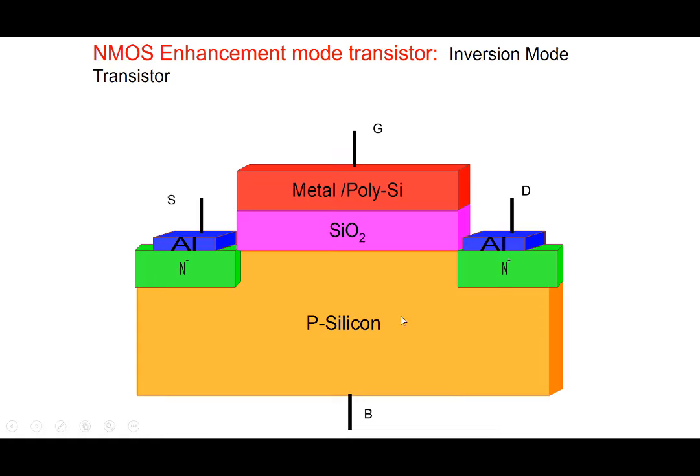Okay, the substrate on which you are making the transistor. So this is body or substrate. So our MOSFET is a 4-terminal device. But for our sake, what we will consider most of the time, which is true in most cases, is that the body is connected or shorted to the source here. So body is at the same potential as source. So effectively it becomes a 3-terminal device then.